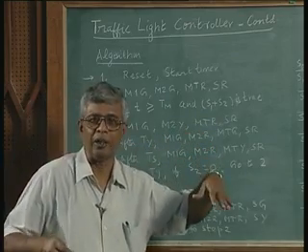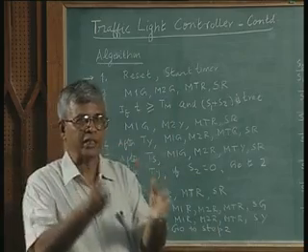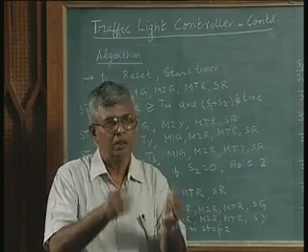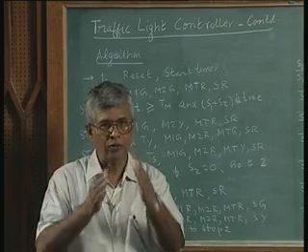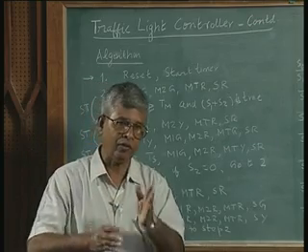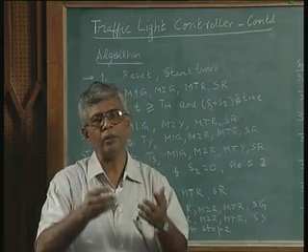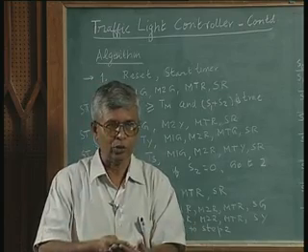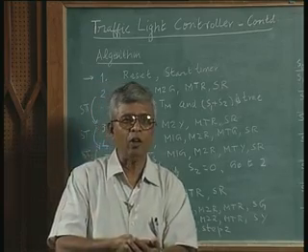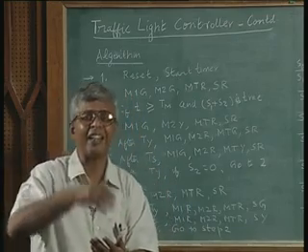There are several possibilities. Suppose I do not have a sensor at all, what is wrong? I allow for the main street to be green for a while, after that time I go from main to side, allow it for a while, and after that I go from side to main for a while, and then go back to the original. That is one simple way of doing it. Number of states will be reduced. One modification will be one of those can be sensors, depending on which is less likely to occur.